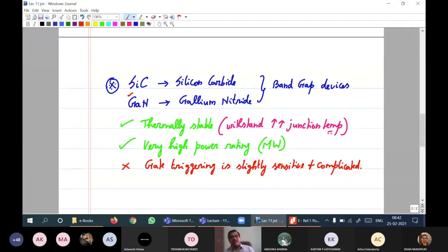I have used a power diode with a voltage drop of 0.45. It can withstand 60 volts, it can carry 10 amperes. Practically it carried 5 amperes. All right, so please be aware of these things. Please understand that textbook stuff is something, practically it is a bit advanced, and that is my role. I feel that is my role. I should tell you what is the advanced thing in place, but I should tell you first what is available in the textbook. I think I am doing that blending job reasonably okay.